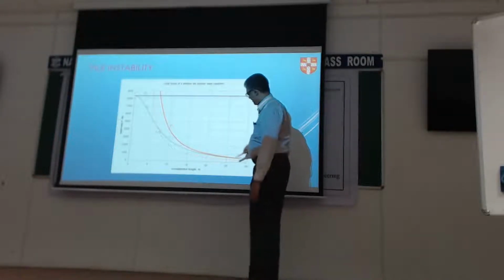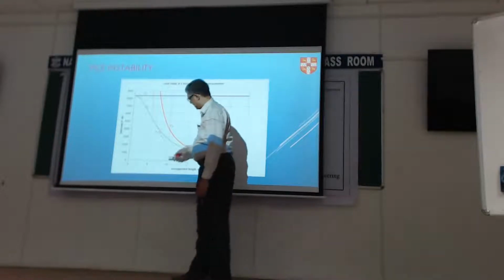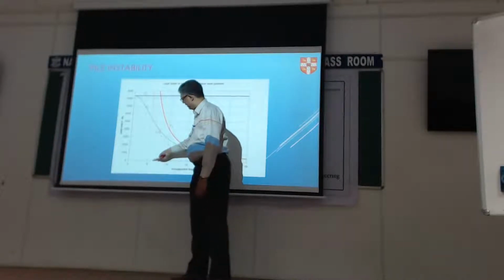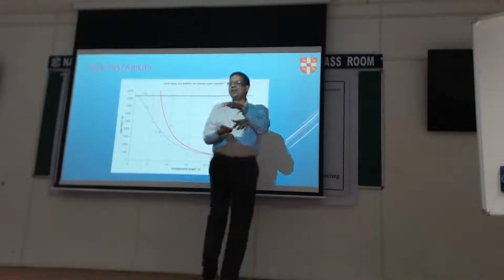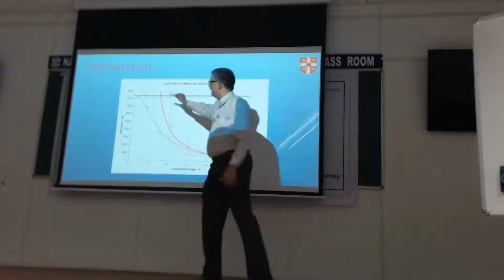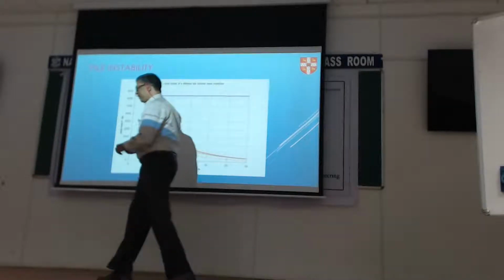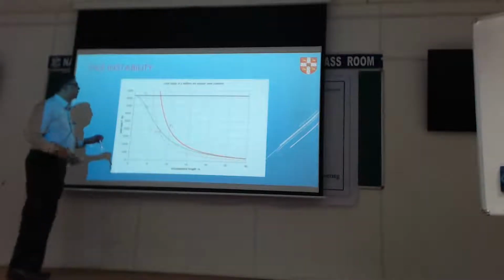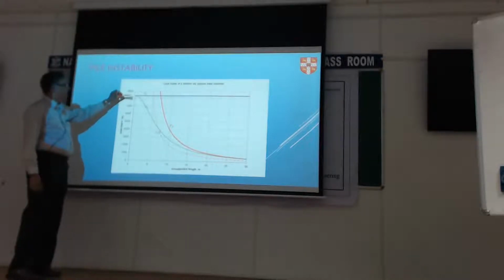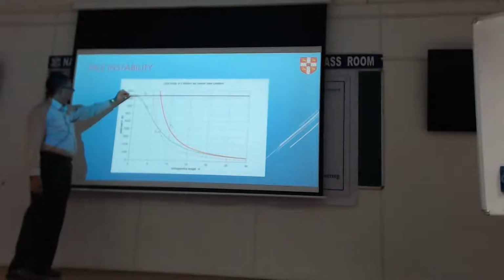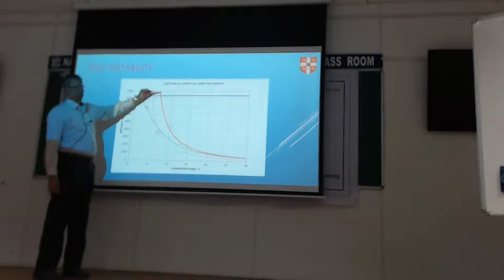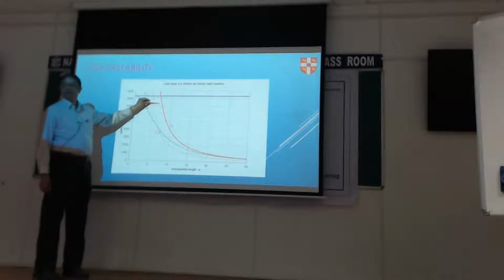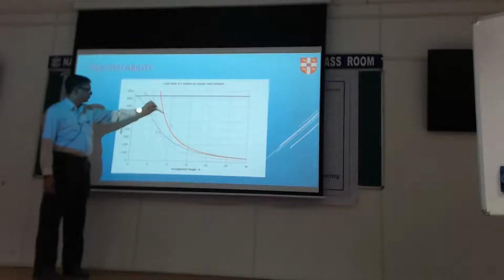So you can see beyond a certain length, the column is so short, it can't buckle, it will simply yield in compression. I shouldn't draw on here, they'll kill me. That's your working envelope. You can't reach these points because you reach material yield. Does that make sense? Here is compression, this is buckling.